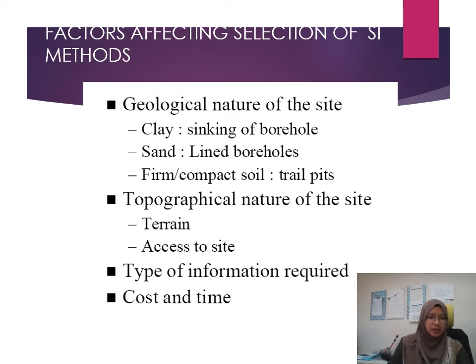And then lastly is the cost and time. This is the most important factor that you have to consider, because it involves cost. The deeper the exploration, the more costly and time consuming it will be. If you increase the number of boreholes, the cost will increase.